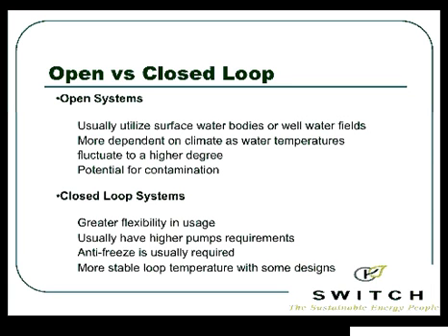We don't want it to freeze and burst our pipe, so we're going to end up with an antifreeze solution in it. We do end up now with a more stable design loop temperature. And we'll see a graph where you get to see how loops are affected by ground temperatures.